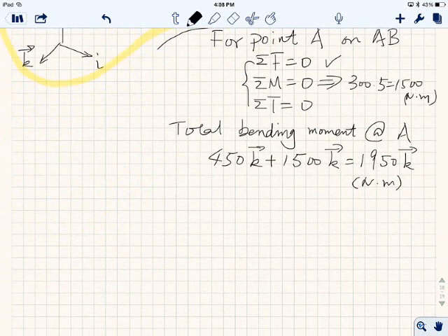All right, so that's the key. Still equilibrium, but going to three dimensions, you just have one more term other than force and moment, right? There's something called torque. And also, don't forget each time we look at only one member, that's a cantilever beam. So make sure you add an extra bending moment at the fixed end. And that's pretty much it. The rest of it is just the math, right? Okay? All right. Do you have any questions?